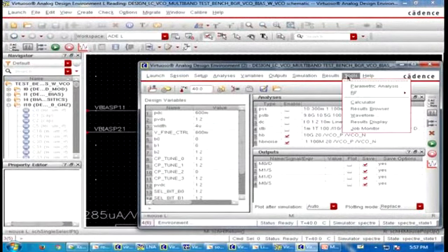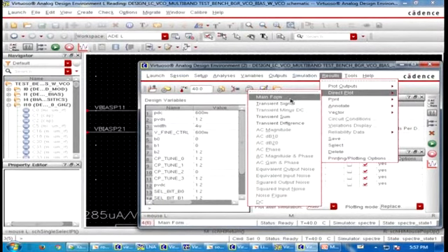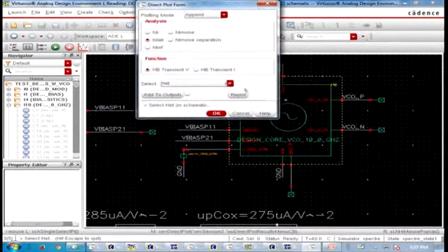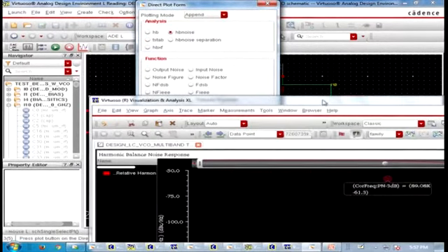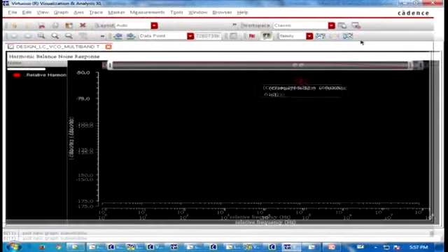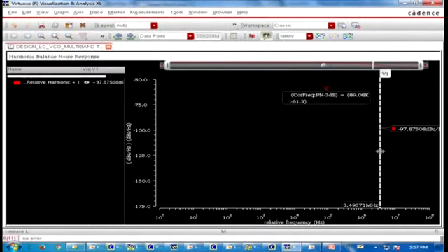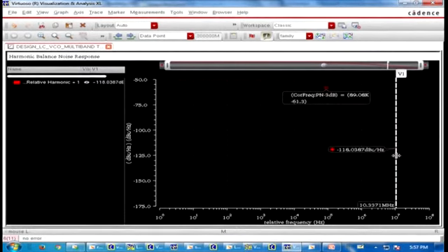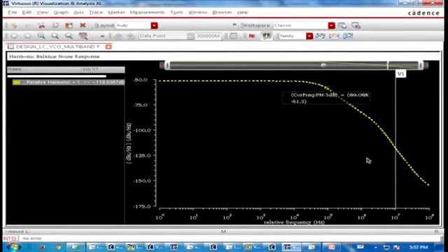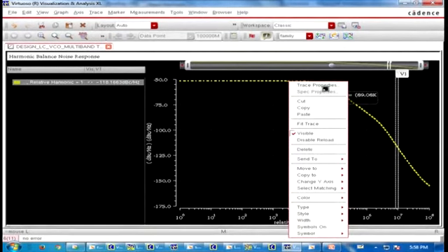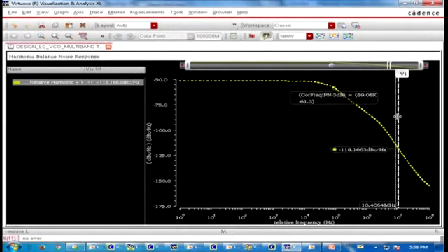I'll just show you the phase noise performance. Let's say this is HB noise. If you are going for that, you see the phase noise performance is here. So approximately at 10 megahertz, it is minus 100 dBc per hertz. And here is the corner frequency because it is a simulation problem. No, we specified at 10 megahertz. Acha, at 1 megahertz it will be around there.